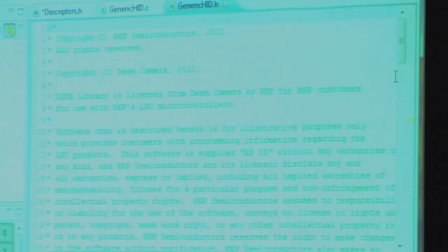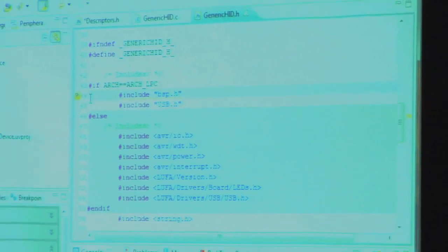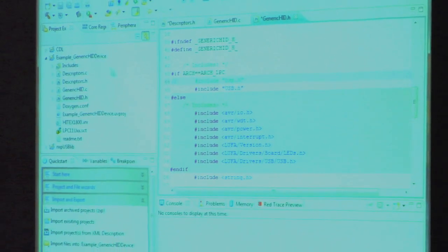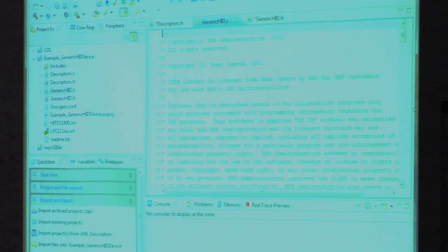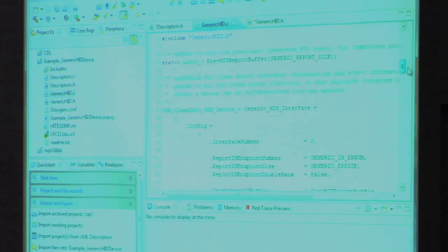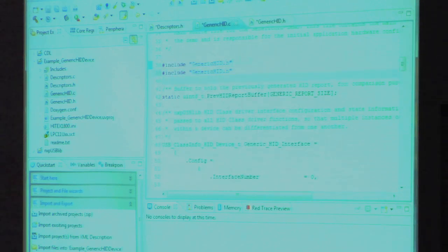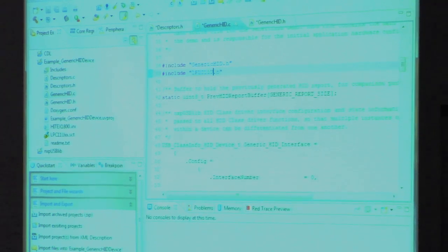Actually, let's go here. I'm going to get rid of this bsp.h. I don't want to reference that. And here's where all the action is in the generic hid.c file. Okay, so these are where all the calls are. One thing I'm going to do is include, since again we don't have a BSP, so we're going to directly use the LPC11U XX header file. All right. Okay.